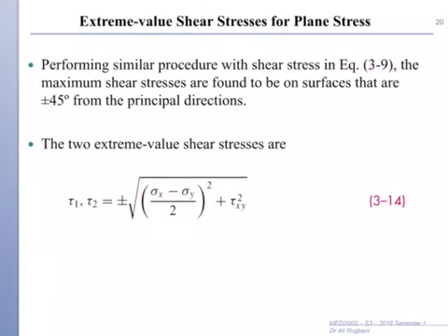If, for example, I give you a problem with one normal stress, that means you have stress in one direction only. You don't have stress in two directions. You only have sigma x, sigma y is 0. But if I give you two normal stresses in two Cartesian axes, then you must use them.